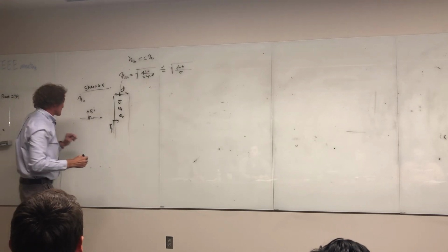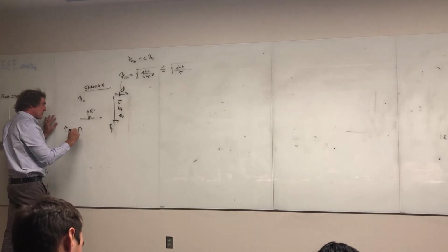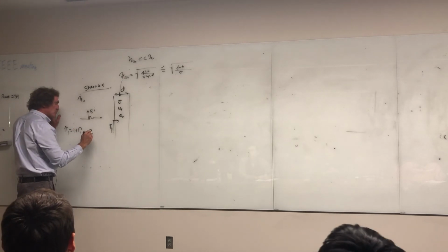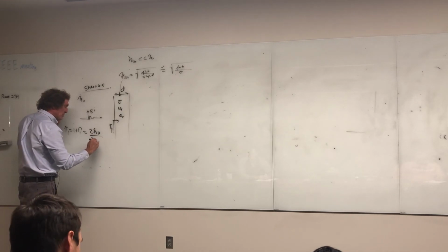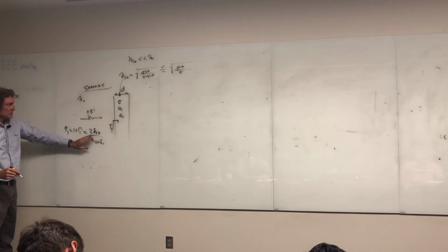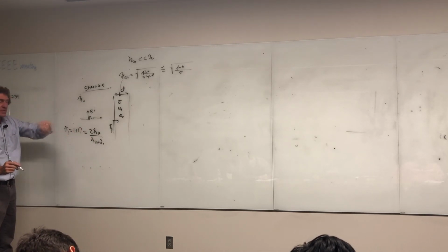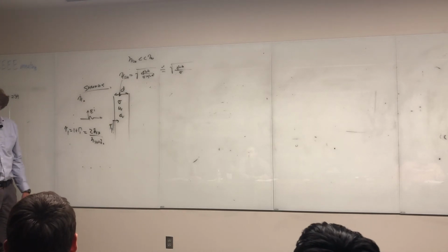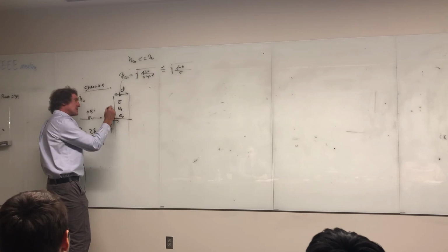So tau 1 equals 1 plus the reflection coefficient, which equals 2 times eta shield over eta shield plus eta naught. Normally you ignore the eta shield in the denominator, so it's just 2 times eta shield over eta naught. That's the transmission coefficient. Got me? Clear on that, class? Once it gets in here, Wentworth's book has it looking like this.